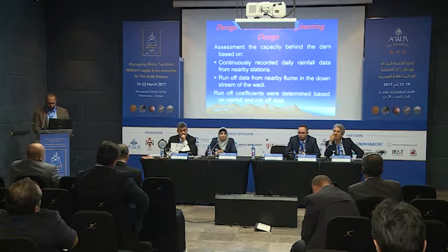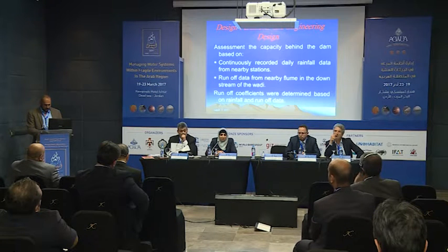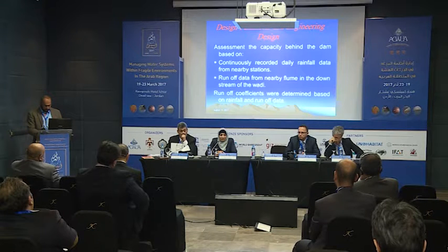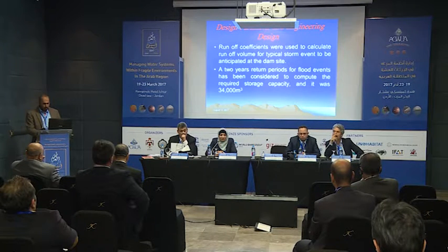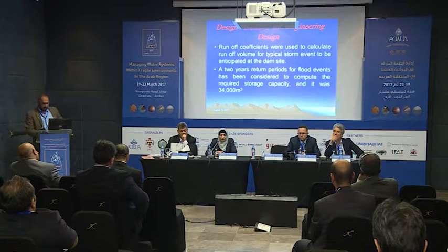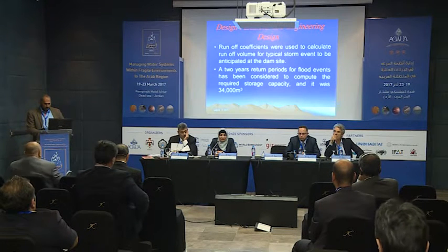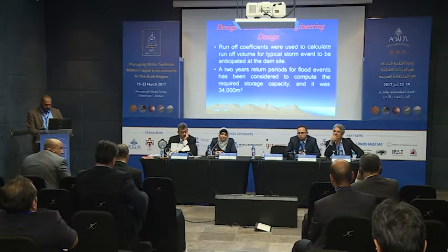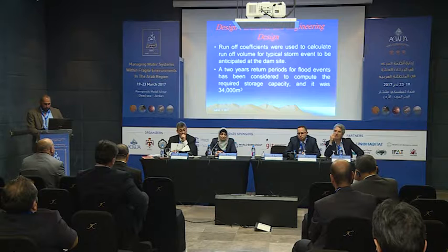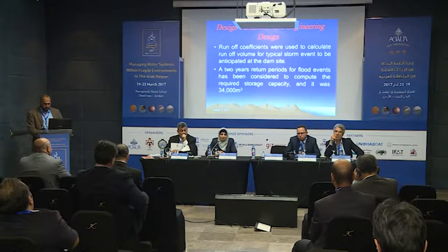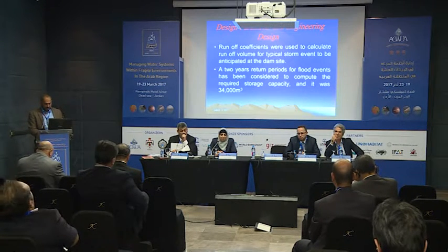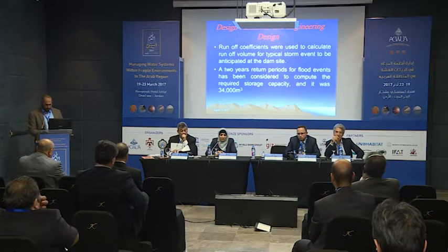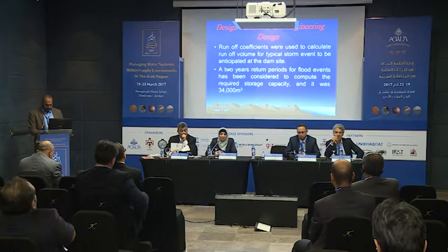From these rainfall and runoff data, we can generate the runoff coefficients, and these runoff coefficients will be used to calculate exactly the runoff volume for a typical storm event to be anticipated at the dam site. A 2-year return period for flood events has been considered to compute the required storage capacity, and it was about 34,000 cubic meters that can be retarded behind this dam.